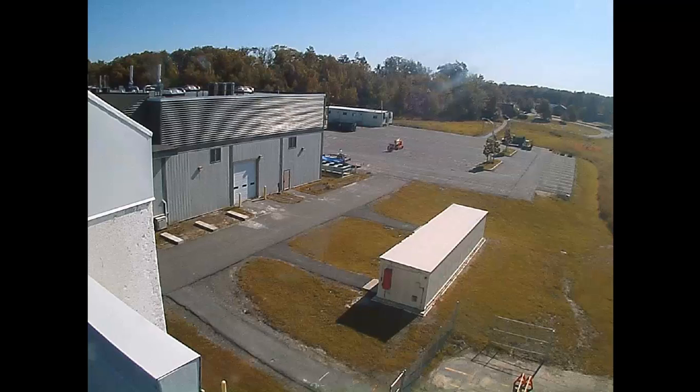So we did this on campus. This was pictures that I took from the Advanced Engineered Wood Composites. They call themselves something else now, but we're going to build a structure on this that's already there now that goes all the way up to the end of this parking lot. You know, we got a new drive coming in, and right in this area right here we're going to put a big foundation that goes down about 40 feet in the ground to bedrock, and it's going to get drill anchored into that bedrock, and we're going to fill it with concrete.